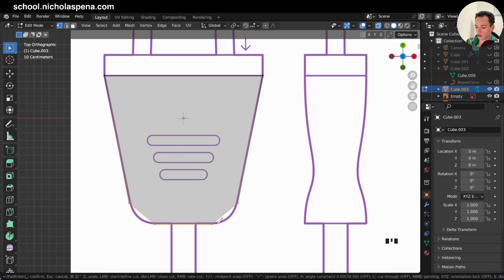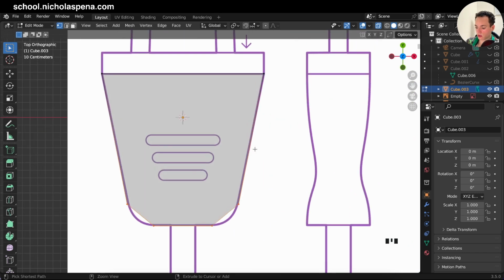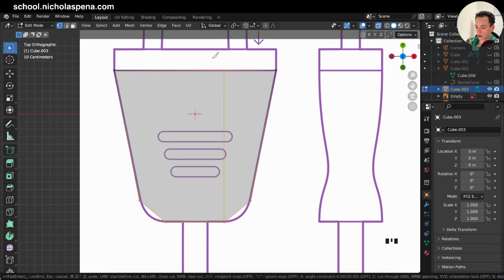If I do just K, for example from this to this, enter, it's not going to go on the other side. So do K, C here, do A to put this straight like this, click, enter. K, C, click here, A, click, enter. Now I have this.